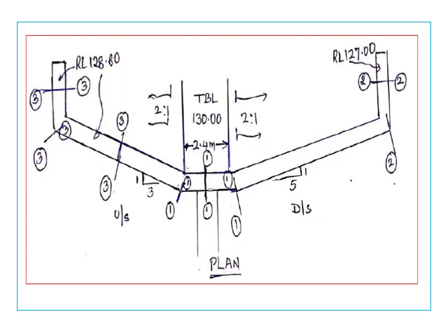So now therefore the wing wall is sloped from 130 here and goes down to 128.8. So by the time it comes to section 3, it has already reached 128.8. So therefore as you go with a slope of 2 is to 1, it will go below 128.8. So that's the reason from section 3 you have to keep the top at 128.8. So now you have to decide for each of the sections here.